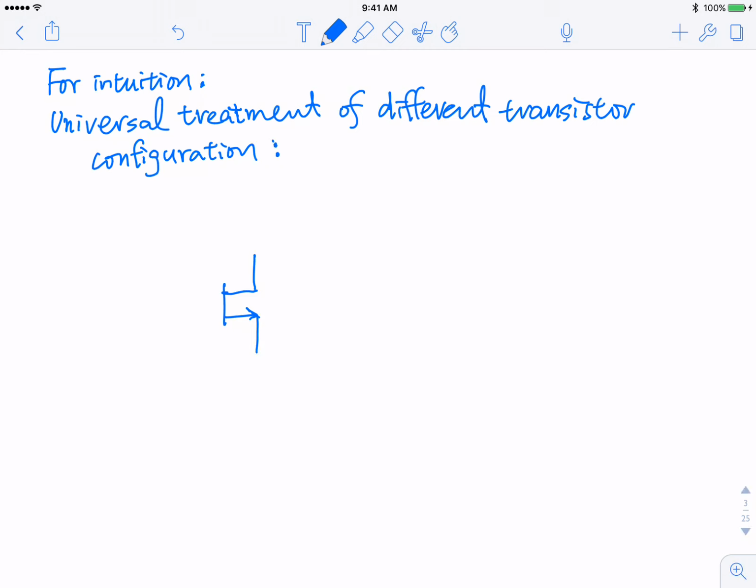So normally this is a transistor, right? And for the sake of this AC treatment, I'm going to ground every terminal as a starting point, okay? And I'm going to add a resistor at every node. Obviously this is not a circuit. You cannot have every terminal grounded. There's nothing to do. So I'll have RG here, I'll have RS here, I'll have RD here, okay?